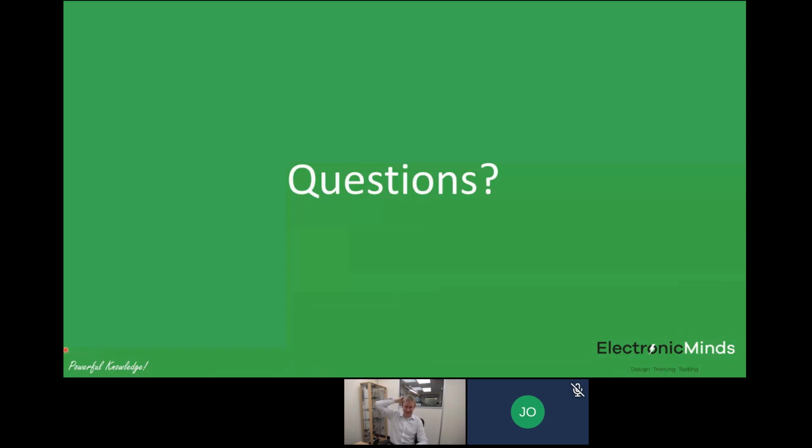EMI is, again, something we're going to have a dedicated webinar on later in this series. It's a challenge. As you go up and up in frequency, dV/dt starts to increase, di/dt starts to increase. So those parasitic capacitances down to earth start to conduct more current, so you start to pick up more noise. You just have to be far more careful with how you design the system ultimately, and how you're looking at the whole system level EMI management.